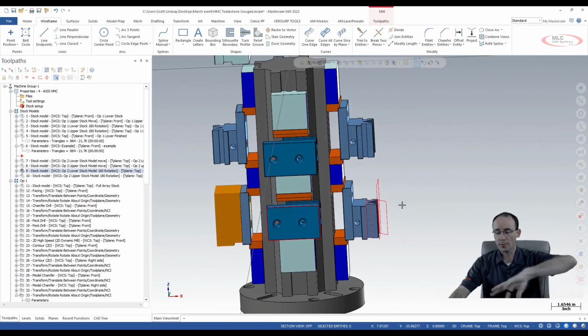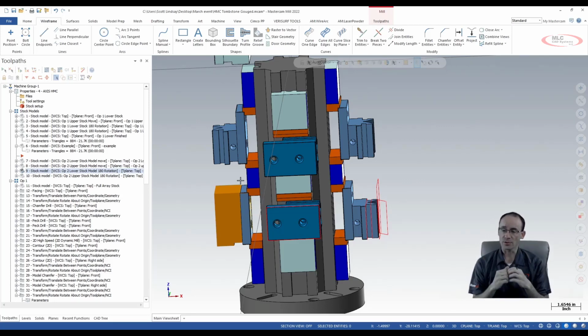Now when you do another rotation, that's going to throw off your X, Y, Z coordinates, so you're going to have to save it out as another mesh and then analyze that distance and put in your new X, Y, Z coordinates, because the rotation happens first and then the X, Y, Z coordinate translation. So get your rotation, get it oriented correctly, then move it in place.